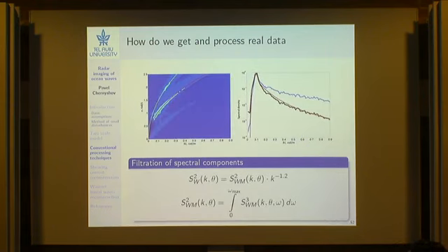What is really interesting is the distribution of energy along this curve, which we can obtain easily. And you see here the results of simulation, because in simulation you can put a pretty nice and smooth spectrum, like a JONSWAP or something else. Simulate the surface, simulate the radar images, and then see that the omnidirectional spectrum will look like this. So it deviates significantly. That means there exists some modulation transfer function between the actual wave amplitudes and the amplitudes we get from radar.